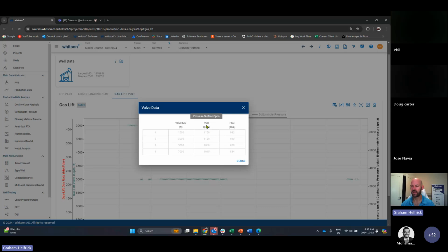I've looked at a wellbore diagram with these inputs, and they provide them typically. But on that point, maybe we should consider an option where the downhole pressures are an input for the valves, and then we could potentially calculate that as well. So for now, we just input the surface pressure.